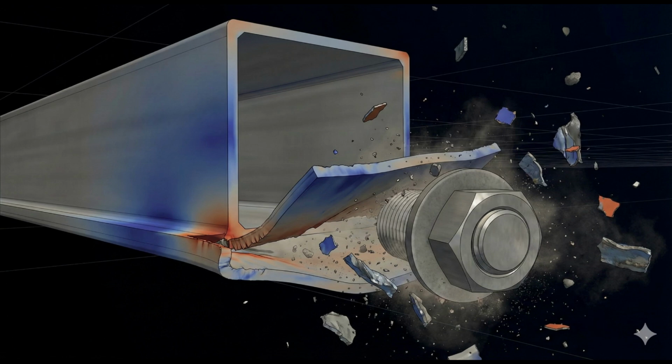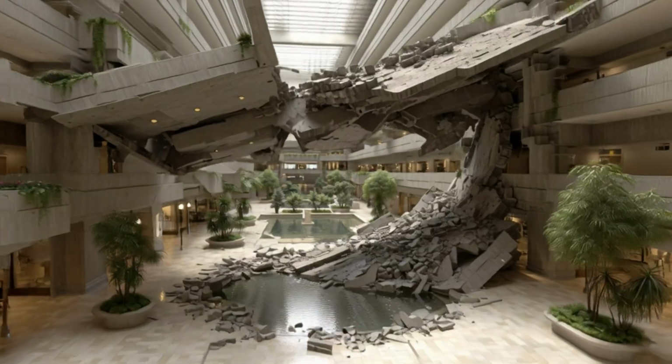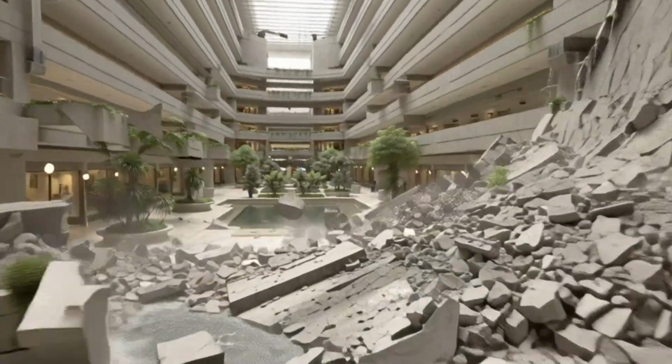The failure, when it begins, happens faster than human perception. The nut punches through the washer. The rod pulls free. The fourth floor walkway begins to fall. Without the support of the upper rod, the fourth floor walkway falls approximately 12 feet directly onto the second floor walkway below. The second floor walkway, never designed for this impact load, fails immediately. Both structures fall to the lobby floor.